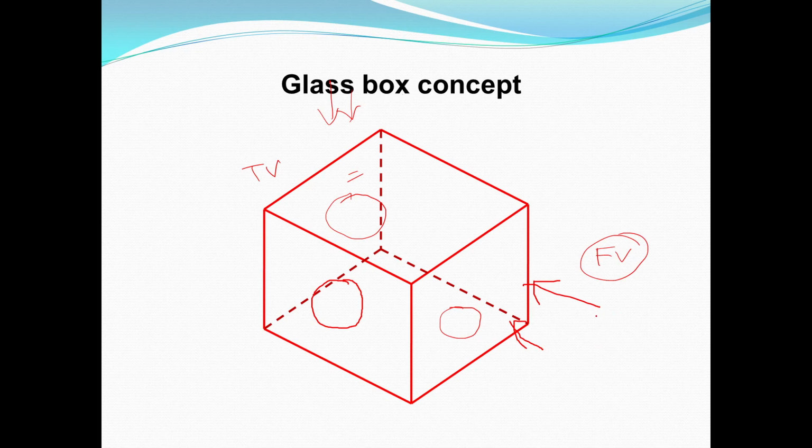In the front view again, this is the observer, this is the plane, the vertical plane, and this is the object. So you get the projections on this vertical plane. Here you get the projections of the top view on this horizontal plane. This is the horizontal plane, this is the vertical plane, and the line of intersection of both the planes is the XY line. Okay. Moving further.